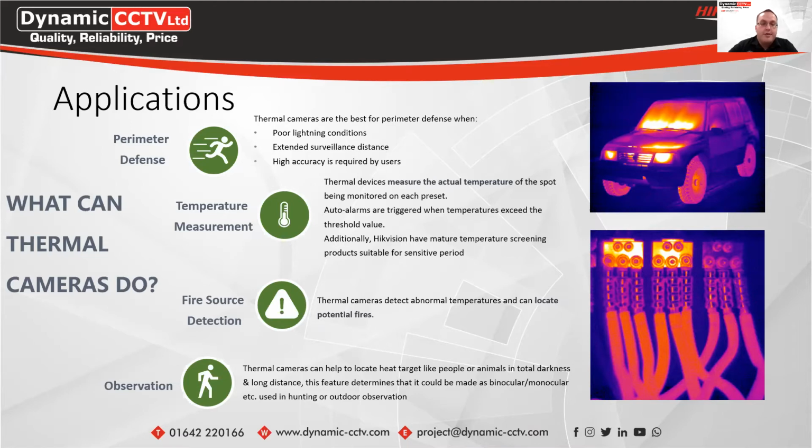You can also do temperature measurement. With this, you can use the thermal cameras to measure a specific spot that you've set up on the camera and monitor that temperature using the actual thermal cameras. And you can also have it trigger an alarm when the temperature exceeds a specific threshold that you have set on the actual camera for the temperature measurement solution.